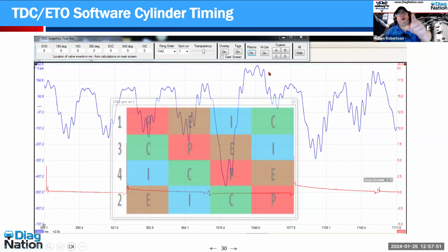And because I was measuring exhaust pulses, I need to know which one of cylinders 1, 3, 4, 2 had a lack of expanded gas. So as I look at this, it wasn't 1, it wasn't 2, it wasn't 4, but dead obvious, number 3. When the number 3 exhaust event happened, there was a drop in that pressure in the exhaust. My problem is number 3.